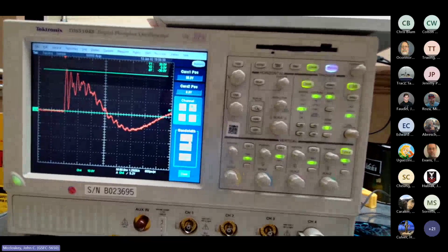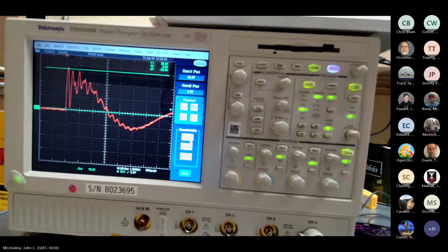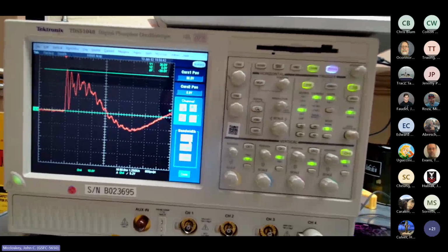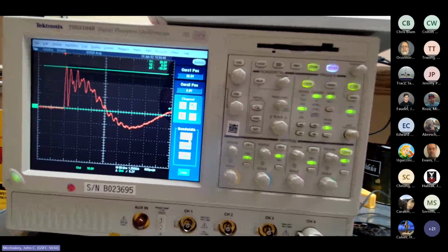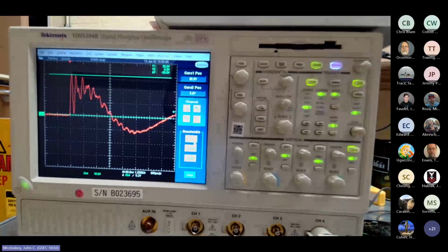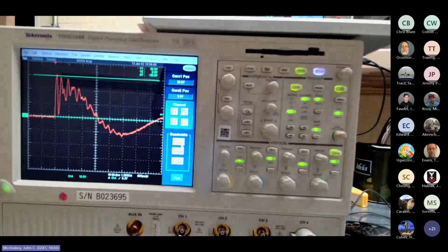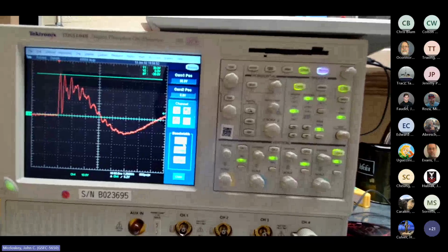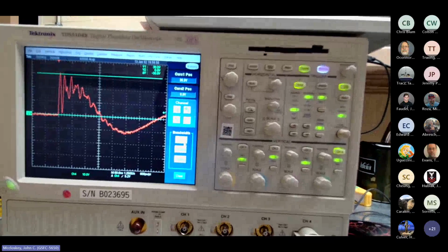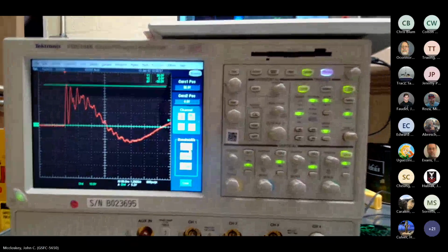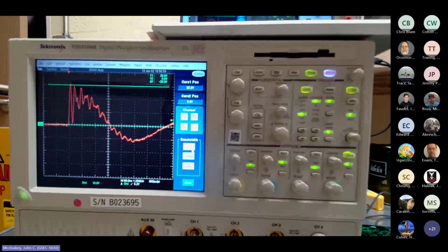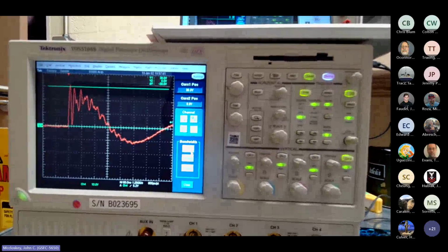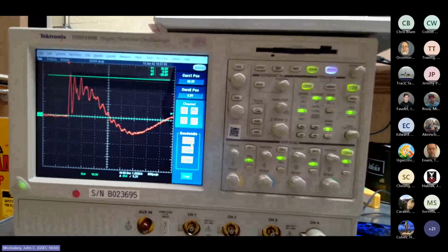And it gets to be a little less trivial, right? For a 10 microsecond pulse, as we've shown, that's pretty straightforward. You have a dedicated signal generator, and the signal is slow enough that it doesn't really matter up to a point how you make your interconnection. You just run a pair of wires from your signal generator to the circuit, and away you go.